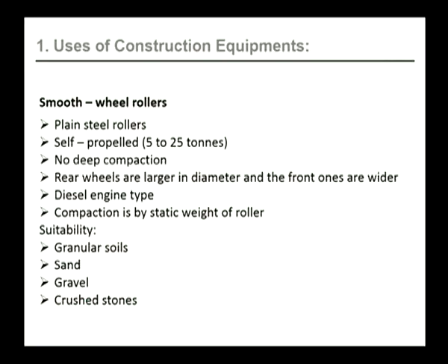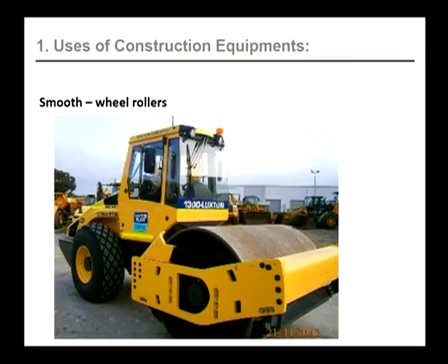Suitability: these are suitable for granular soils, for sandy soil, in areas where there is a lot of gravel, and also in areas where there are crushed stones. These are called smooth wheel rollers.